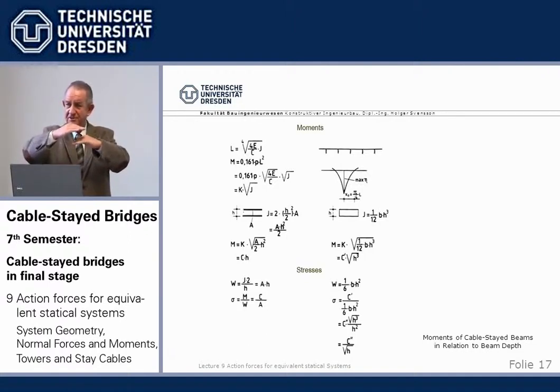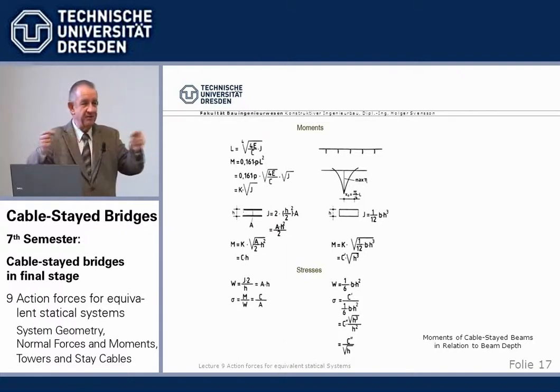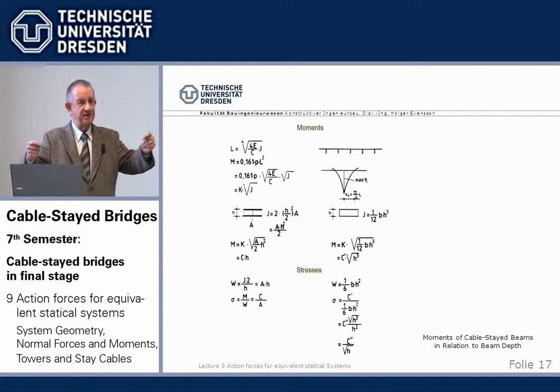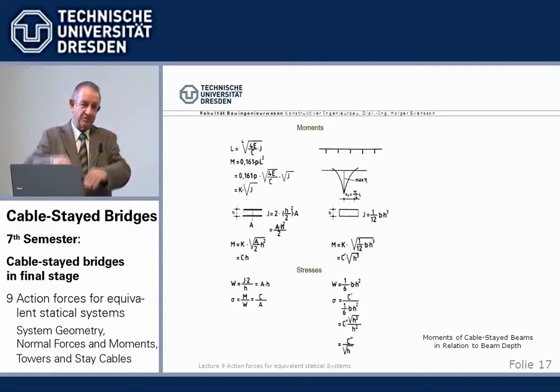Then stresses are very small. Yeah. The limiting condition, however, is the buckling. I cannot have less depth or less bending stiffness, so that I still have sufficient safety against buckling, or practically speaking, I limit my increase of stresses due to non-linear theory. We come to that. But we can get rather close, and I will show you examples.